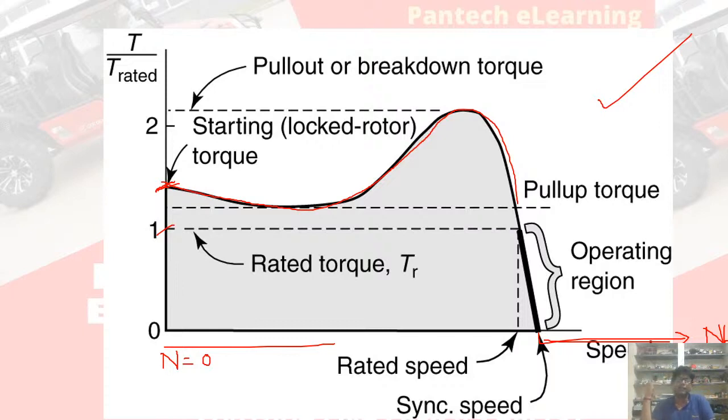So basically these things are continuously happening inside the motor. First it is standstill, and once you give the power supply to the stator, immediately the number of flux lines cut by the rotor conductor is maximum, high voltage is developed, which in turn drives high current through the rotor bar, and again it produces high torque, which accelerates the machine towards the synchronous speed.